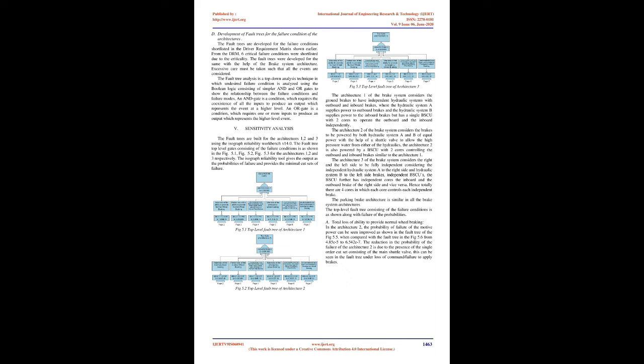B. System Functional Hazard Assessment, SFHA. The System Functional Hazard Assessment consists of classification of the short-listed failure conditions in the FCIM, based on the different flight phases. The qualitative analysis is done for the failure conditions. The effects of the failure conditions on the crew, occupants, and aircraft are noted. Based on the effects, the hazard classification is obtained for the failure condition. All the hazards corresponding to the failure conditions are identified and documented. A few rows of the SFHA are shown in table 4.2.